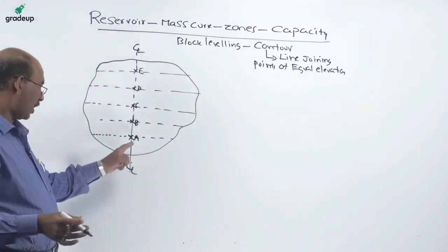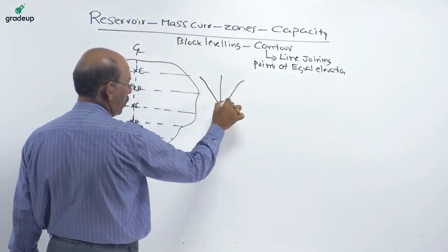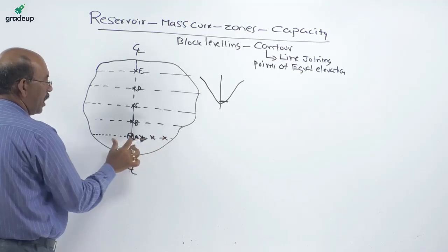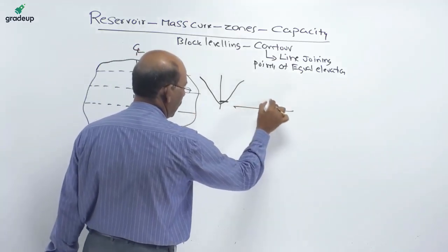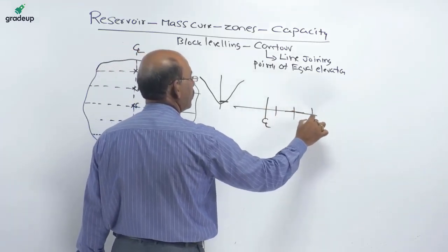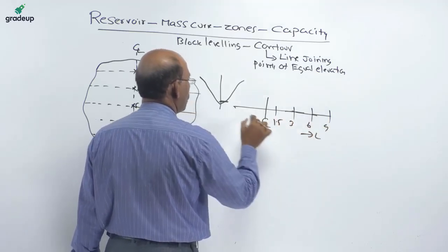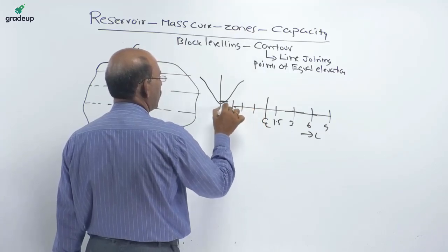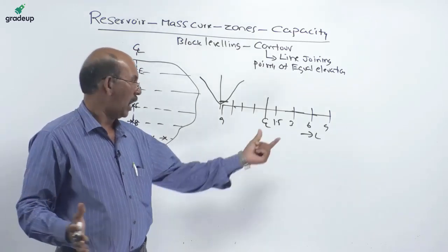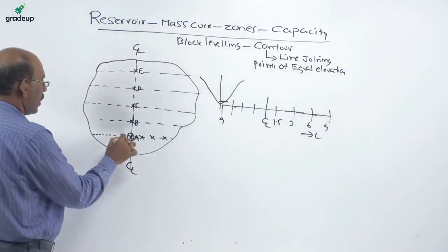At every cross section, normally, this is the maximum nearest point. From this particular one, normally we will take readings at intervals from the center line. This is the center line: at 1.5, 3, 6 and 9 meters to the left. Similarly, the same thing on the other side: 1.5, 3, 6, 9. So on both sides of the center line, at distances of 1.5, 3, 6, 9, you can establish the various points.